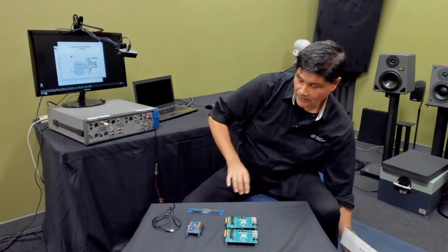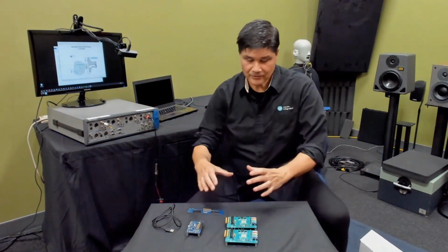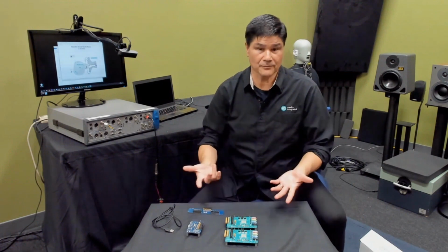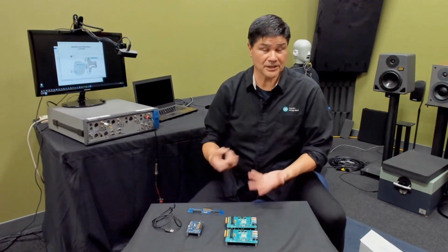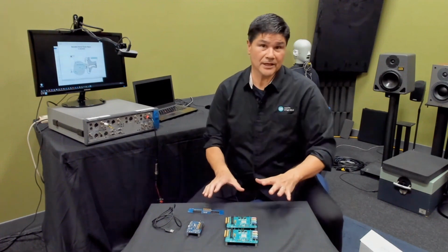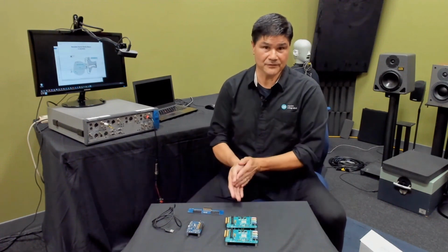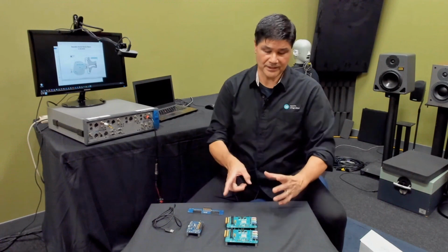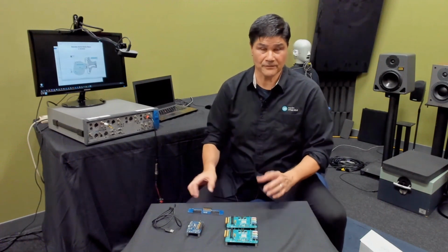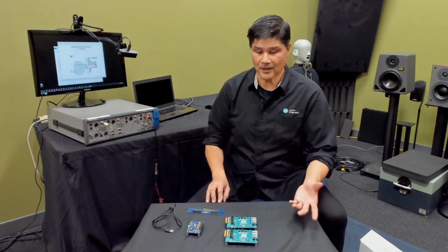So with all this hardware, you have the ability to connect it either as a mono configuration or a stereo configuration. Mono is typically how you'd use it if you want to do bench evaluation electrically using an audio precision or something similar. Stereo evaluation is where, maybe if you have your filters designed already, you want to connect it to a form factor headset and evaluate acoustically. You can do hardware evaluation using a GUI as well.